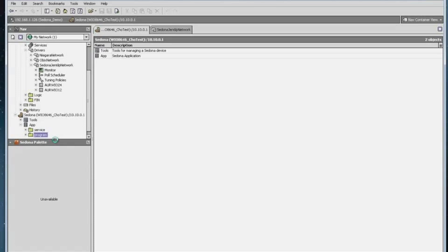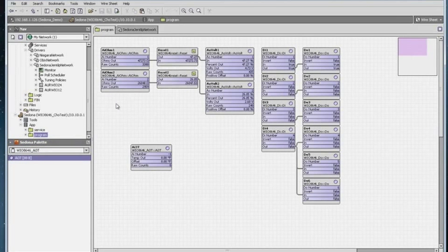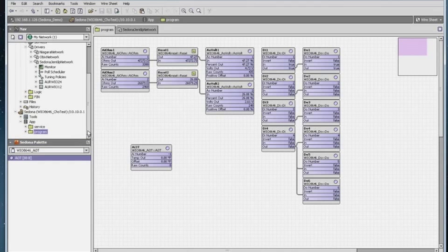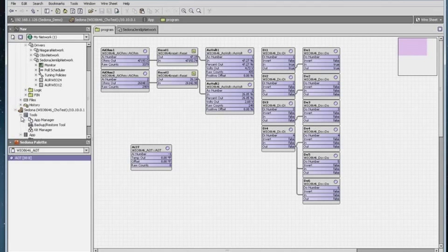All right, what we're going to demonstrate next, as soon as it loads, is how to change the application. You can see now the analog value that I added is still there. It took the program change. But let's say we have previously built a unique profile or air handling unit application that we wanted to utilize over and over again on a job. So instead of having to build logic independently of each controller, you can place pre-configured apps in the devices themselves.